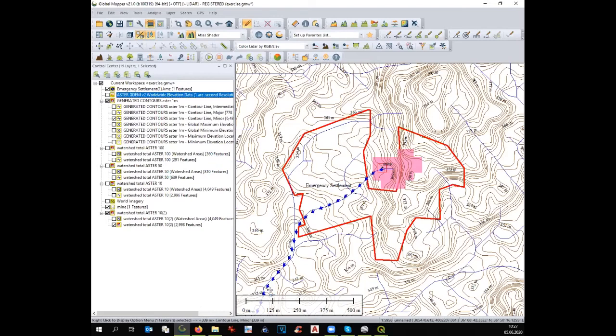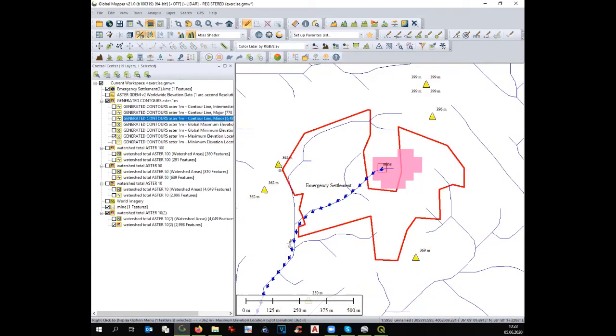It's very easy. Such a site, you can cover in a few flights and you have a rather precise digital terrain model. And then really you can start to develop drainage in a proper way. But if you don't have the drone, you can use a total station. You put the total station on a high spot, for example, let's see, minimum elevation, maximum elevation. You put the total station, maybe here, and here, and here eventually, or even only one, and then you can really cover everything.